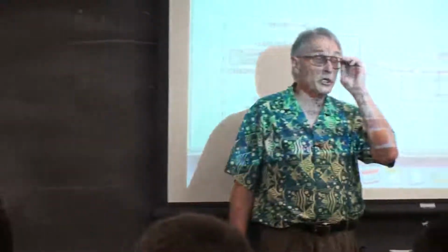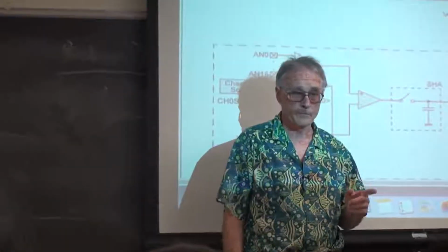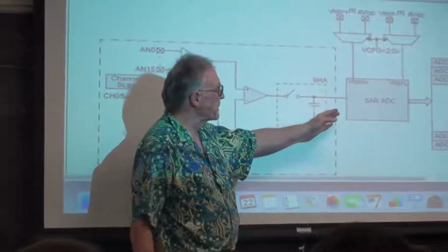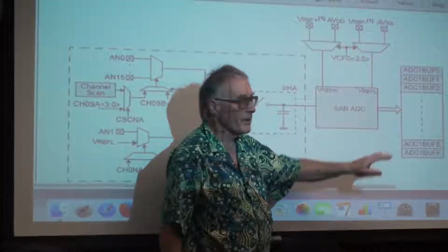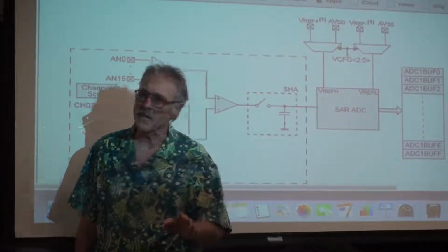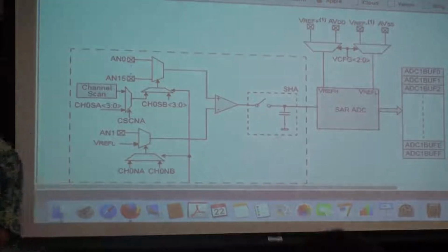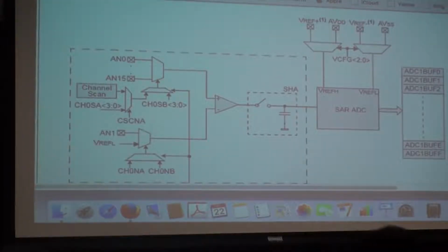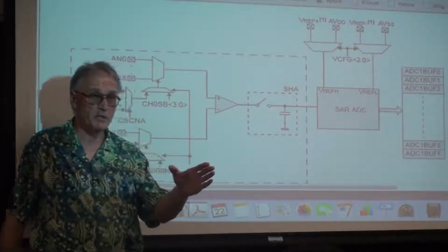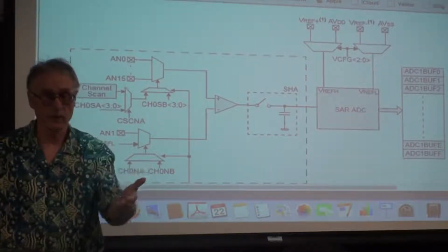So this whole thing should be timed to a few microseconds. And in fact, my code does a conversion in just under a microsecond. It pops the switch open and does the conversion in just under a microsecond, and you probably don't want to mess with that timing. You do not change the sample rate by changing the ADC timing, but rather when you start the acquire. So you're going to control when the acquire occurs, when the switch pops open, bink, that's going to start the conversion. Your code is going to control that.